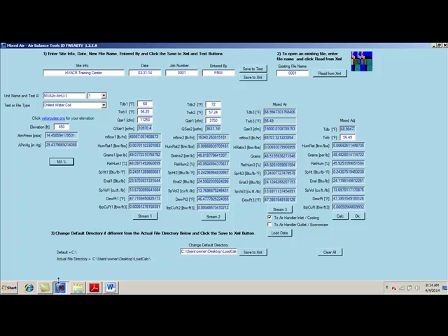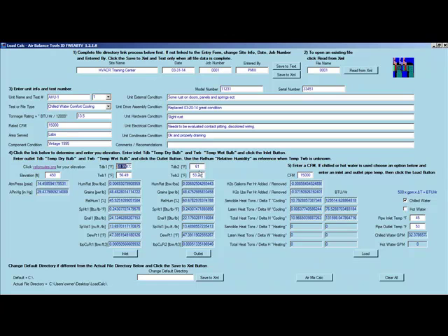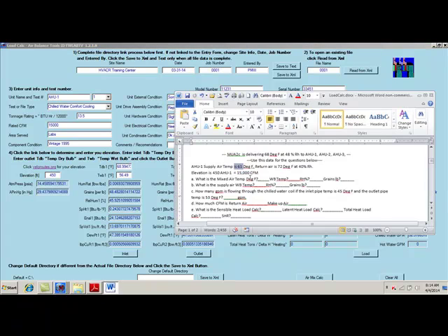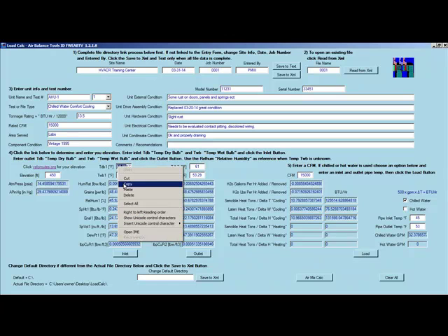So now that we've pushed this data up already, we go to our load form. We've made our adjustment. We've got 61 degrees at a relative humidity of 60. And we want our relative humidity to be what? Now, there's no specification of what we want it to be, so we need to calculate what our mixed air temperature is at this point. So our mixed air temperature is this. Let's go ahead and copy that.